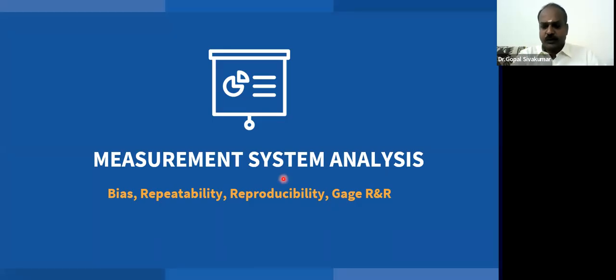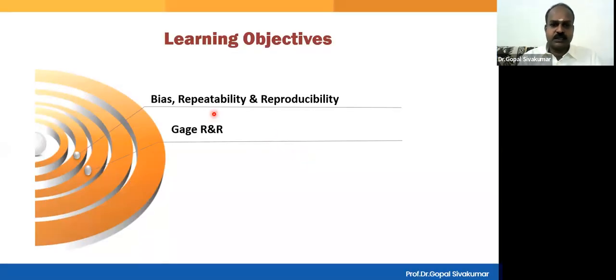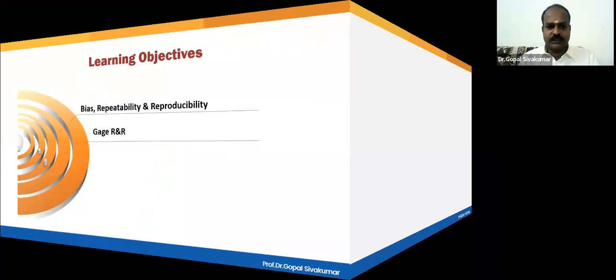Hi, hello. In this video, I'm going to help you understand certain tools associated with measurement system analysis, particularly tools such as bias, repeatability, reproducibility, and Gage R&R. So these are the tools we are going to learn in this particular video. So the learning objectives go like this: bias, repeatability, reproducibility, and then Gage R&R, which stands for gauge repeatability and reproducibility. So let us understand all these things.